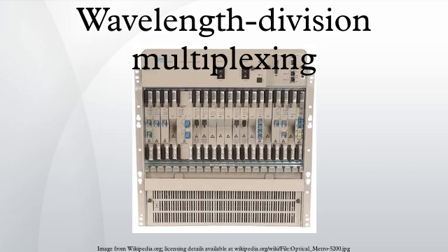Optical cross-connects. When the network topology is a mesh, where nodes are interconnected by fibers to form an arbitrary graph, an additional fiber interconnection device is needed to route the signals from an input port to the desired output port. These devices are called optical cross-connectors. Various categories of OXCs include electronic, optical, and wavelength selective devices.